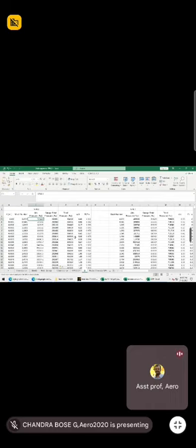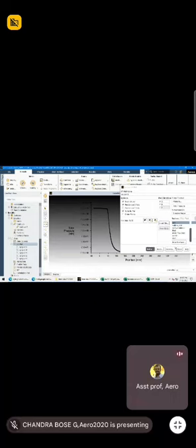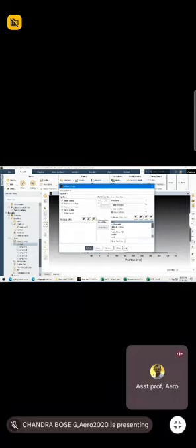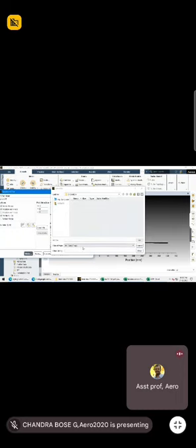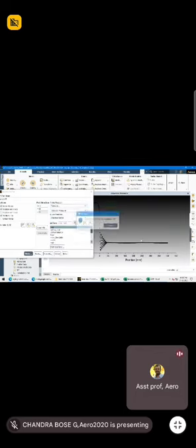Okay, now I need absolute pressure. That means absolute static pressure. Don't confuse gauge and absolute. Total pressure, static pressure. If I select static pressure here, it means static pressure alone. If I select absolute pressure here, it is absolute static pressure. So first, to see whether you are getting absolute static pressure, plot, you will get like this. In the same way, you put write to file, write. So you type CLSP, center line static pressure, and you click OK.